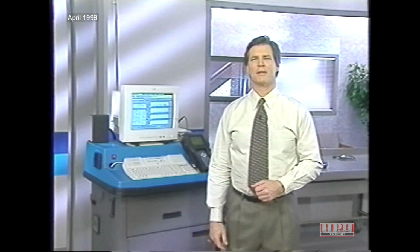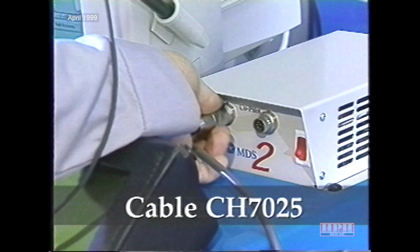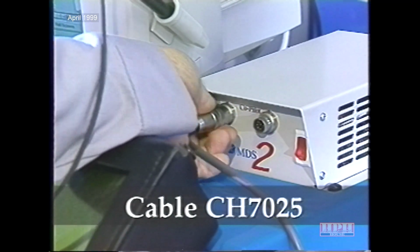Now that we've seen how templates are created to record vehicle data, let's see how to download a template into the DRB or Co-Pilot. Before downloading the template, the DRB or Co-Pilot must be connected to the MDS-2. If you're using the DRB, connect it to the MDS-2 power supply using cable CH7025.